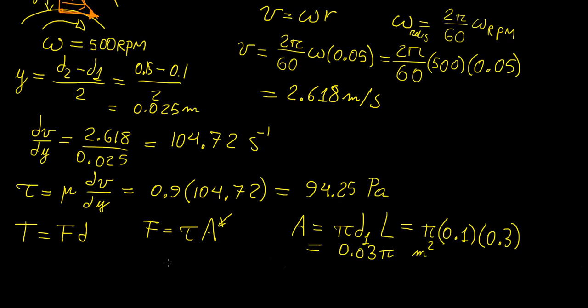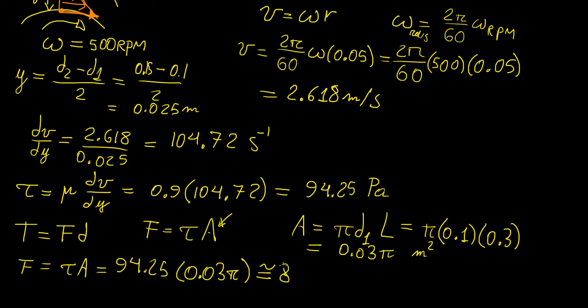Okay, so now we know what that is. We know what the shear stress is, so we can calculate the shear force. So this is going to be 94.25 times the area. And let's see what that gives us approximately. That's going to be 8.88 newtons of force.